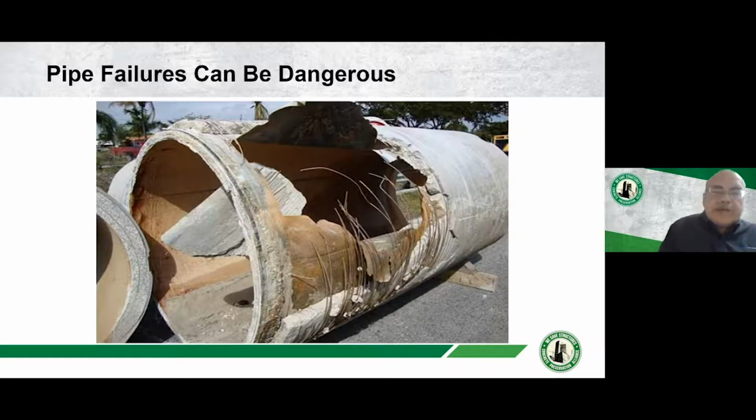This is a precast concrete cylindrical pipe, PCCP. There's an inner concrete core, and then there's a metal membrane that has been blown out and bent. There is an outer core. Then that whole section is wrapped with pre-stressing strands, and then there's a kind of a mortar coating on the outside of that. This was a catastrophic failure. A lot of water was wasted. Flooded out a municipal area. It may have even launched boulders up in the air. So a very serious condition under these high pressure pipes.